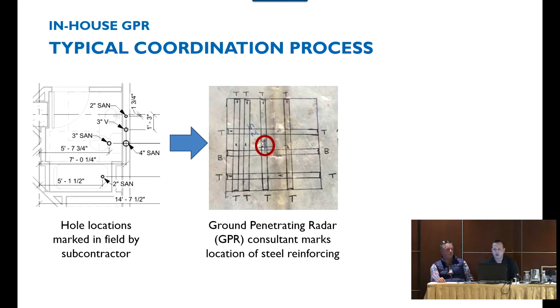That individual would then call or contact a third-party GPR consultant. They're out there, we all know. So then a little bit more time goes by. That trade would come out and physically mark on a slab, top bar, bottom bar, as well as how they relate to the proposed core penetrations.